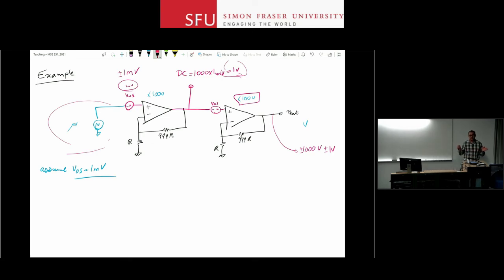In that case, life is easier. What you can do is, in between these two op-amps, you can have a coupling capacitor that you have seen before. A coupling capacitor separates the DC from the two stages, right? So the two stages are not affected by the DC signal from one side to the other. So even if you have a DC voltage produced at the output of the first op-amp, it doesn't affect the second op-amp. The second op-amp doesn't see it. The AC signal that is produced here goes through this capacitor and reaches the second op-amp.